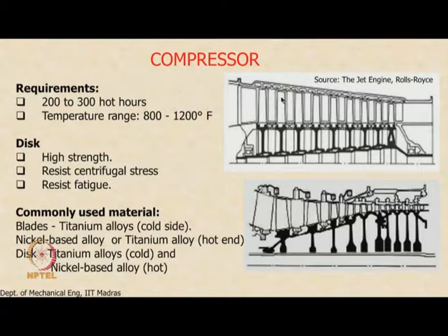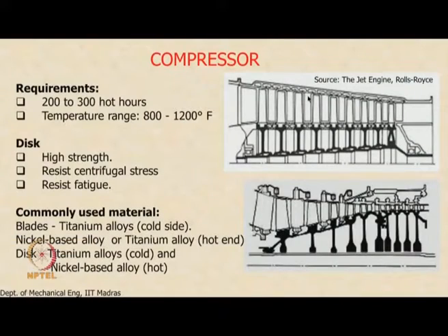One of probably the most challenging aspects of manufacturing such an engine is to ensure minimal clearance between the casing and the blade tip. Right? The clearance between the blade tip and the casing should be as small as possible, as otherwise the air would flow over the blade and not through the blade passage. So if it goes over the blade, it is not going to be compressed.